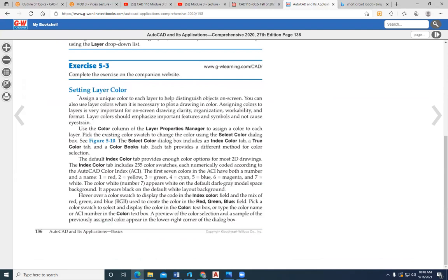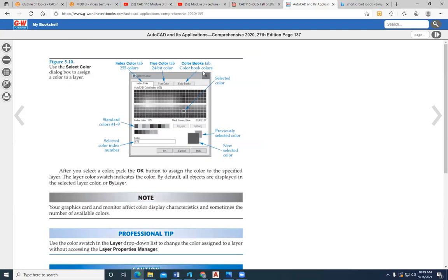We'll assign specific colors to the layers, because when we have 20 people working on 20 different drawings and we start to assemble them, we want all the colors to match. So we'll set layer standards for that. And it has a number of different colors. If you go into interior design fields, you can actually have them match to these paint color books.